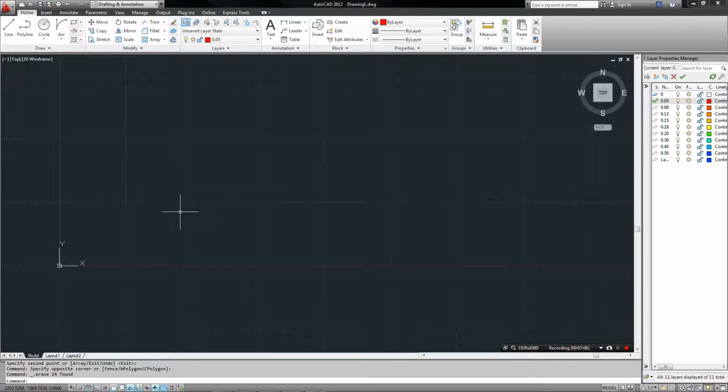Nice and simple. The Move tool, again, got some lines. I want to move it over here, M space. I want to move it a certain distance. Let's make it 1,000 millimeters over to the right. Done. Easy. Now I want to move a copy of this. So I hold that down. Oh, sorry, that's not in AutoCAD.